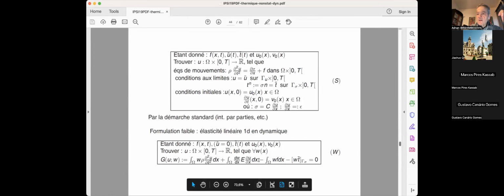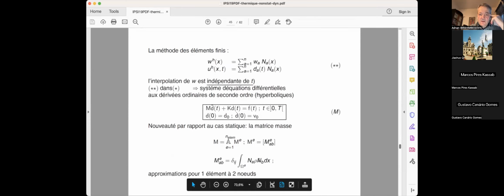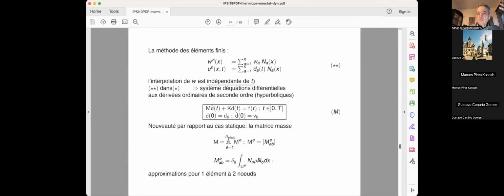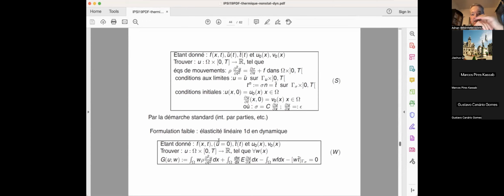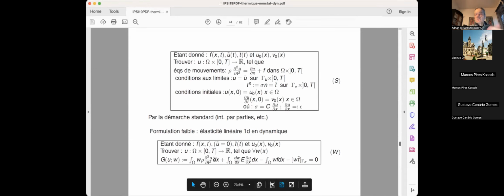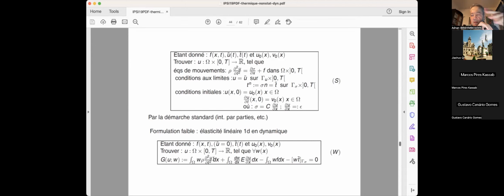So I don't have to repeat what we have done for a static part. We have done that in the very first lecture. So I just take into account what we done for dynamics. Namely, first of all, when you do the principal virtual work, this is done in the spirit of D'Alembert. What D'Alembert said, if you have equation of motion which depend both on x and t, you can imagine taking a photograph. So you froze the instant in time, and then you turn this dynamic motion problem into a problem of static equilibrium, where this term, which is inertial force, mass times acceleration, is taken on the other side and added artificially to a set of the external forces. And then basically you can apply the principle of virtual work.